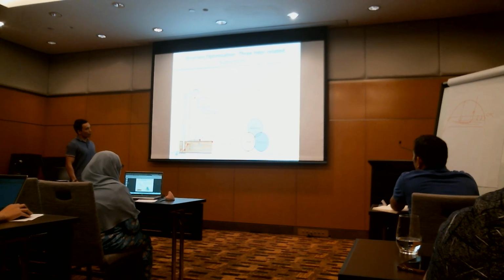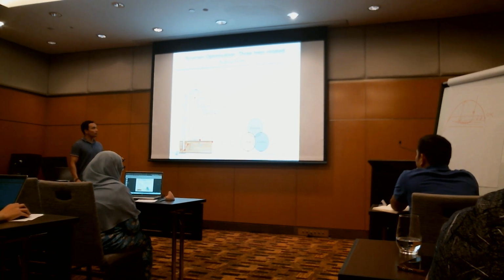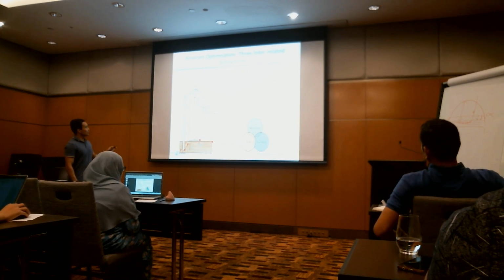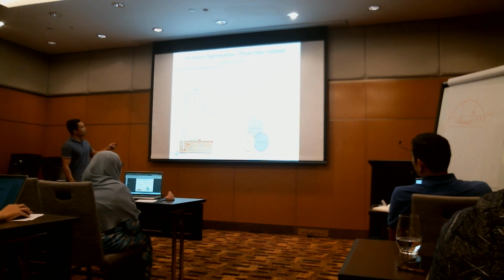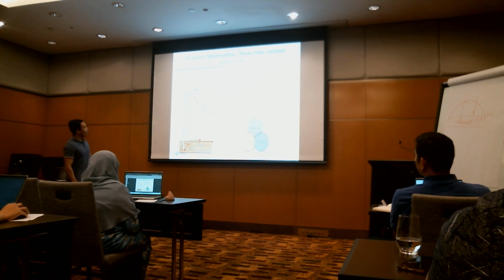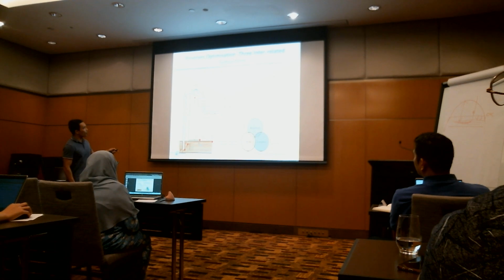And you also have wells here. You might have mechanical problems, all the problems related to the well. That can also lead to a lower RF. This just shows the subsurface system, where each node has a different pressure. You start with the reservoir, then you have wells, just to give an analogy, then this is a choke at the facilities, and then it goes to the safety point. So it's all interlinked.